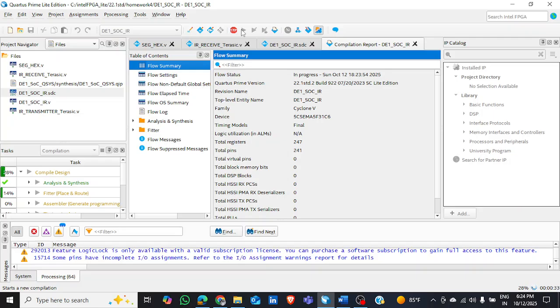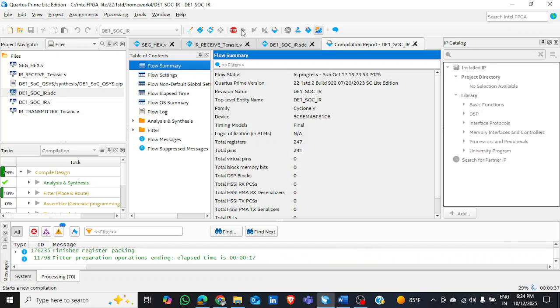So the distance is being increased. And then when you recompile, you see a dramatic increase in the critical path delay. This basically proves that interconnect delay, which is the time a signal spends traveling in a wire to its destination, is the most significant factor in modern FPGA performance.